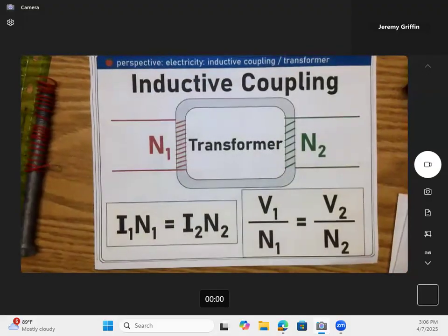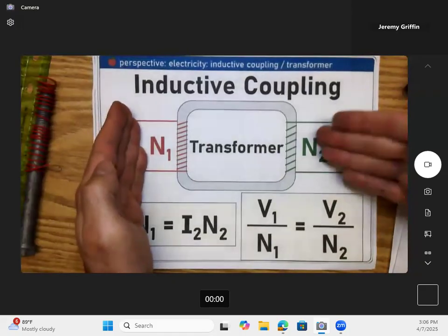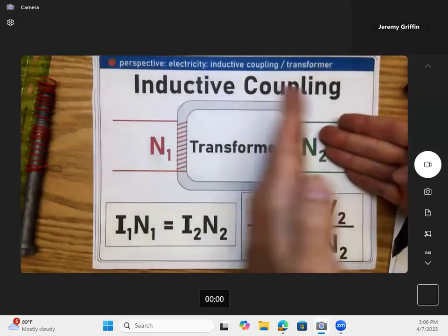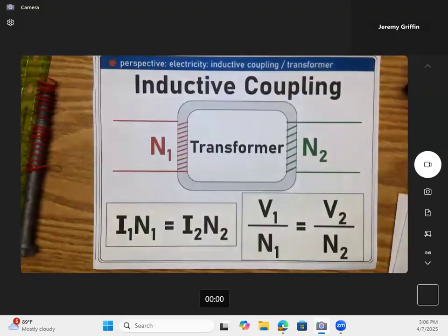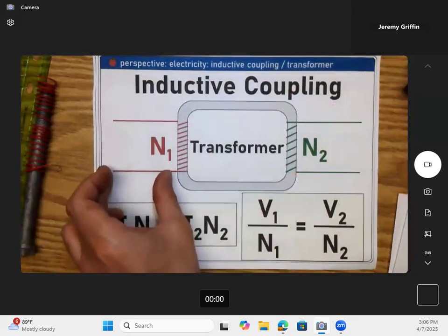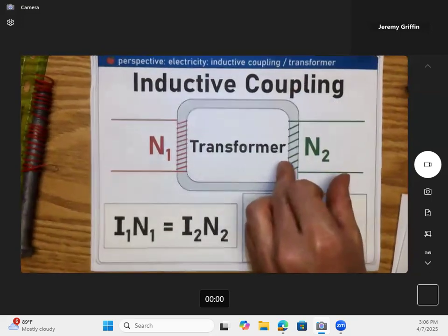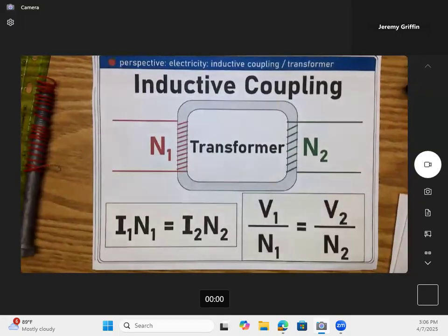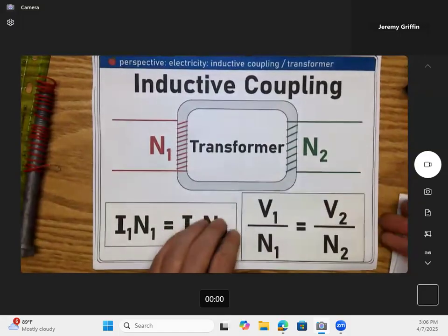So those electric lines out there might be like 100,000 volts. In this room, these outlets are like 120 volts. Okay, so we're going from like thousands of volts to maybe like 100 and some volts. So you want to step the voltage way down, and in turn the current will increase. Okay, so very low current, high voltage on the power lines, right? And then a low voltage but a higher current, say like inside this room.